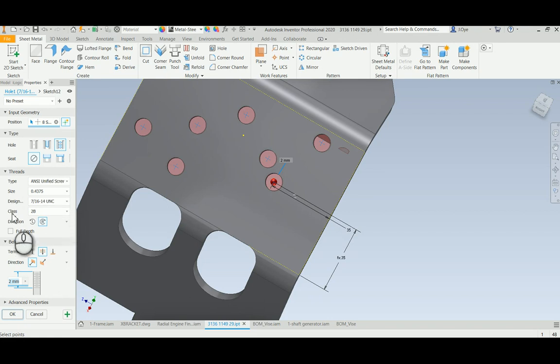All right, well, let's get out of that, and I'm going to go into a drawing. Inventor 2020.1 update now allows you to add to your iProperties within the drawing file. Find that component, that .ipt file, or it could even be a .iam file. Scroll down through your shortcut menu, find your iProperties, and it brings up your iProperties.